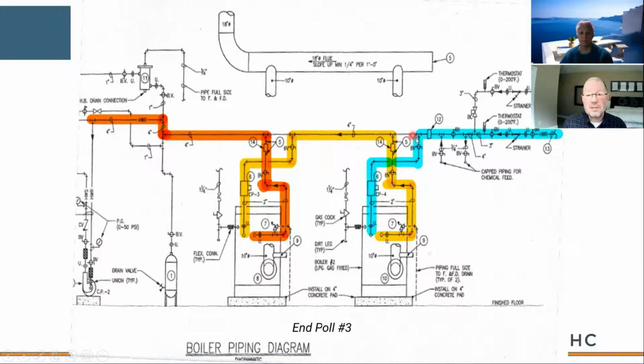We do have closely spaced T's here. Well, if we have closely spaced T's, we also have dedicated boiler pumps. Yeah, we do, as a matter of fact. That's what CP4 and CP3 is, okay? Circ pump 3 and circ pump 4. So dedicated pumps for each boiler. So good indication of primary, secondary.